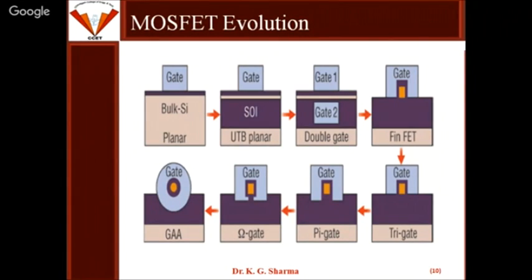Because of that, the leakage current through the substrate substantially decreased. Now the point is that when we decrease the channel length, problems like the DIBL effect and subthreshold slope were arising. To reduce those problems we changed to another technology: if we have not one gate but two gates, on two sides of the channel, then there will be more control over the channel current.